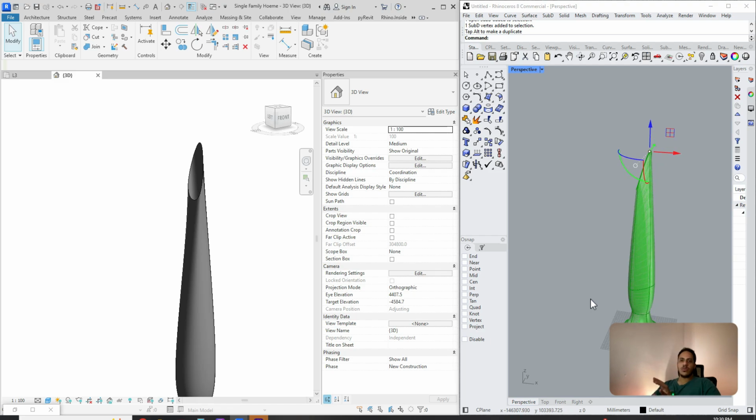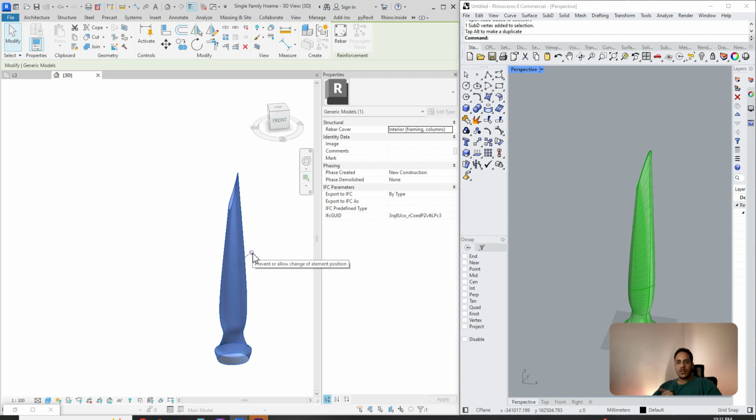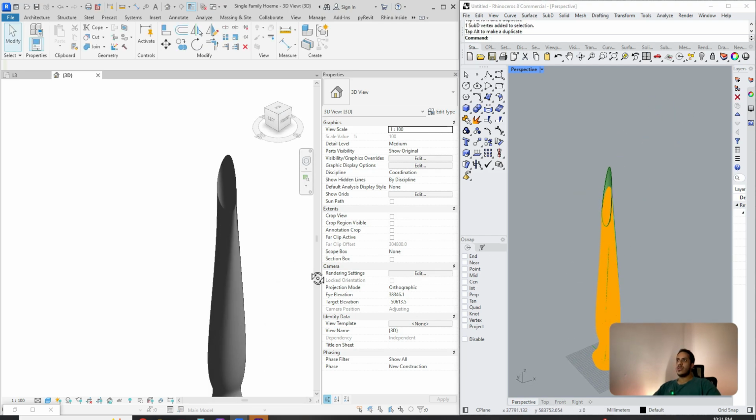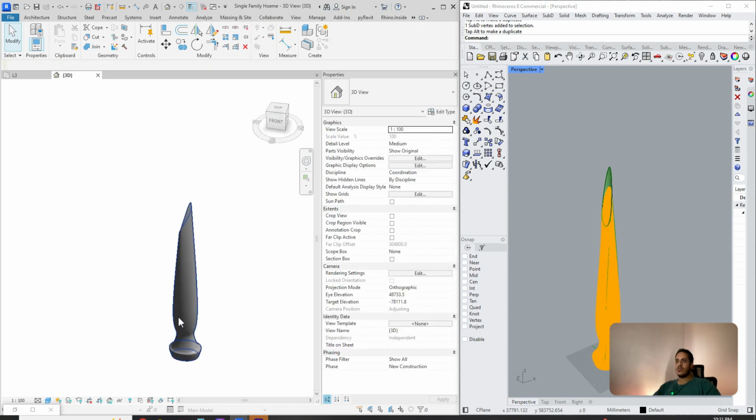And of course, you can apply any script in Rhino first, and immediately or anytime if you want to import it in Revit, it will be imported. If you unpin the objects in Revit and try to do something in Rhino or in the model, it will not be updated. Once you unpin it, it becomes unique and unlinked from Grasshopper and Rhino.